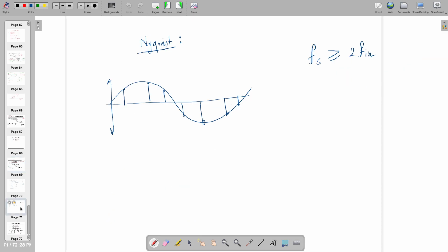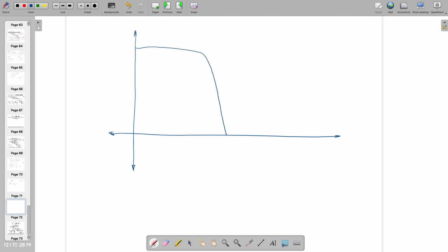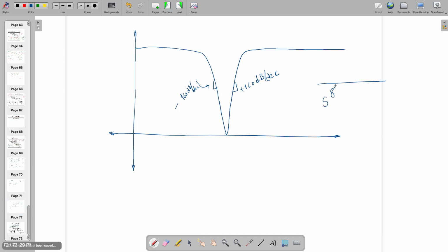Right? A filter is the one which will remove unwanted signal, or it will allow some band of frequency. Let's assume that you are designing a notch filter or band stop filter, which looks like this one. So for this slope and this slope, we want, let's say, 8th order, which will give you 160 dB per decade. So this needs 8th order. So you need to design some driving point function where the denominator will have s raised to 8.